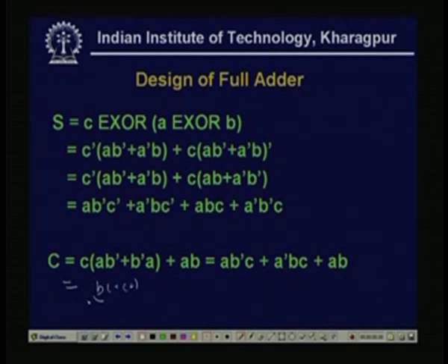So, that also we can write in this way, C A B dash plus B dash A, and that is also A B dash C plus A dash B C plus A B. In this way also we can write my carry.